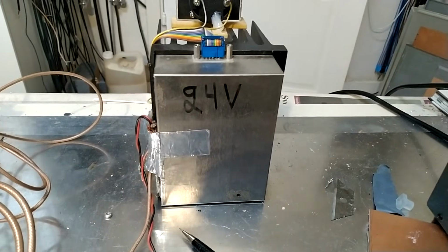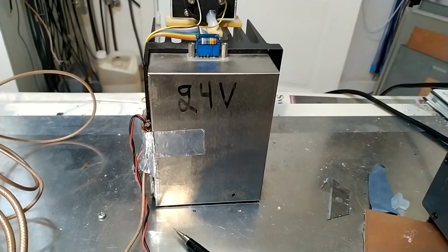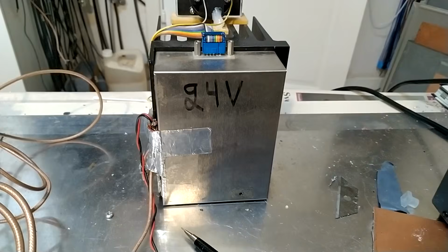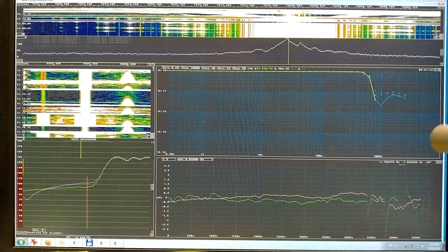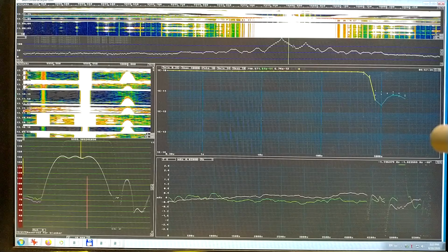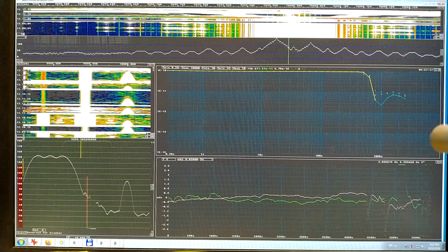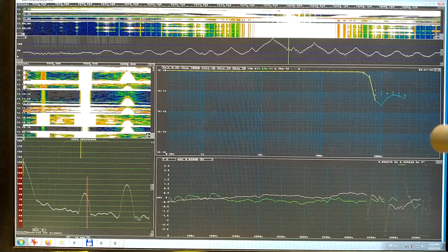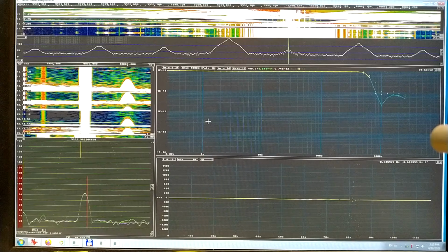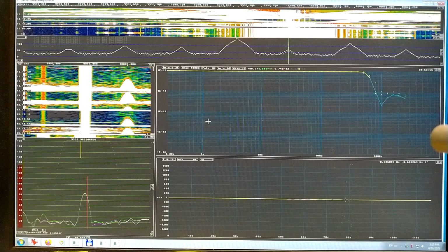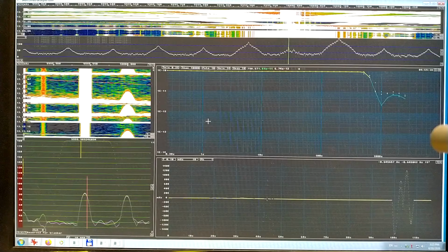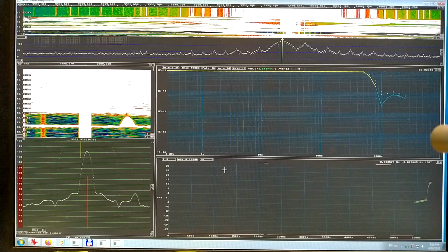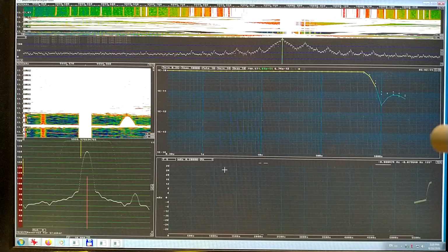I have replaced the Wenzel oscillator by this rubidium source, LPRO 101. While searching for the resonance, it sweeps a fairly wide range, as you can see here. Plus minus something like 100 hertz or so. It was more than that, down to 200 hertz below 10 megahertz and 100 Hz above.